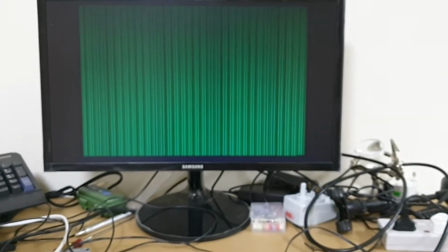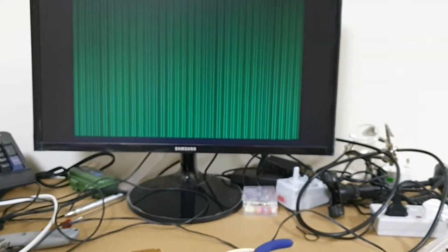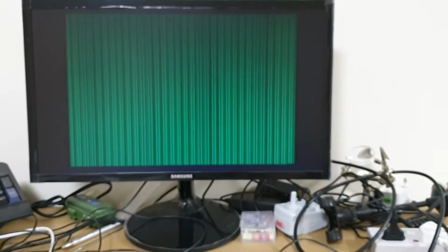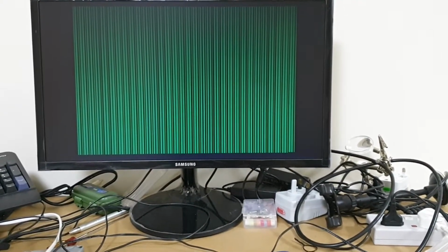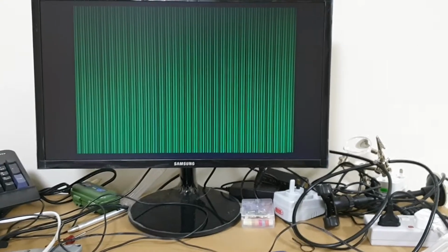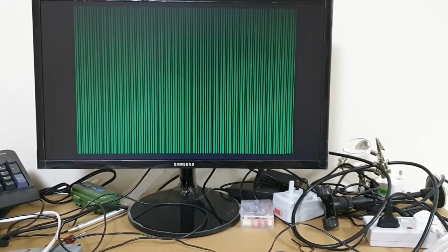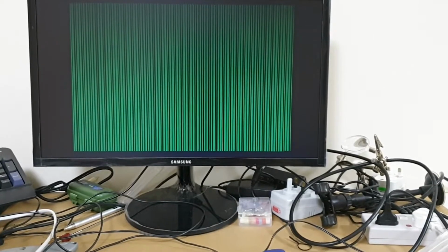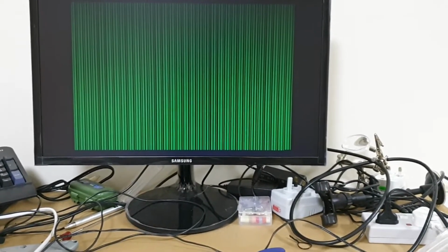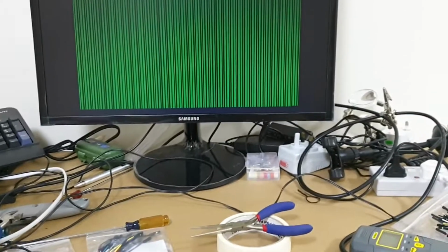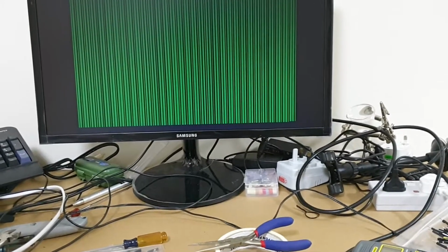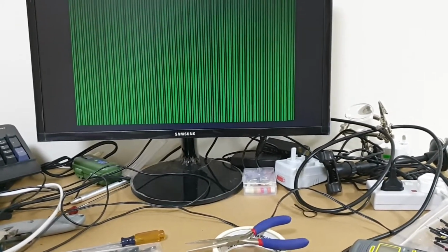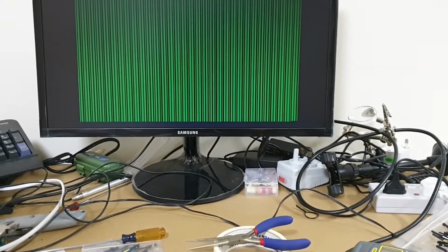But the horizontal and vertical pixel position is not. It's all floating high from the character board. So what I'm seeing here is the effect of basically fetching the same pixel all the way down the vertical position of the character. Obviously the addressing is not going to work, because the addressing for where to fetch the pixel from in the bit plane RAMs comes from the character screen, which is not connected, so it's floating high already.